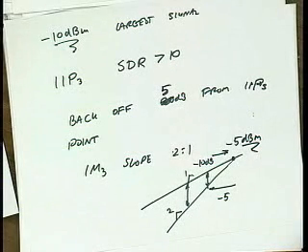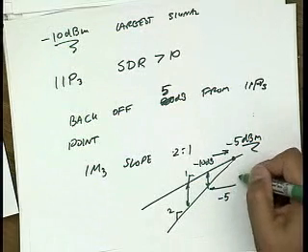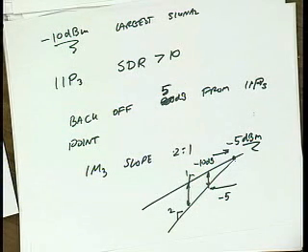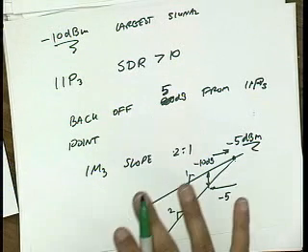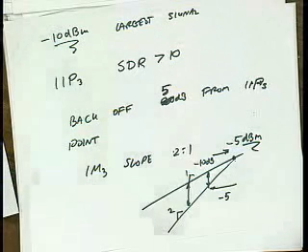And that's the answer. I have a doubt here, like when my signal is minus 10 dBm, my distortion is minus 20 dBm. IM3, for this particular example, yeah. Remember if I back off 10 dB, my IM3 improves by 20 dB. Looking at it the other way, when my signal is minus 10 dBm, to maintain a signal to distortion ratio of 10 dB, my distortion should be minus 20 dBm. So if I now increase my signal by 10 dB, my distortion will increase by 20 dB. So I reach the equal point. So where does this slope come from? Okay, if you're talking about distortion alone, it's cube, right? When I take the ratio of distortion to signal, it becomes square. So if you think about distortion, it's cube.